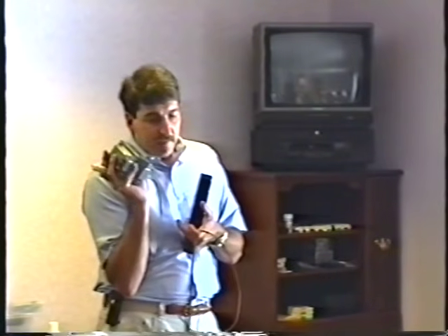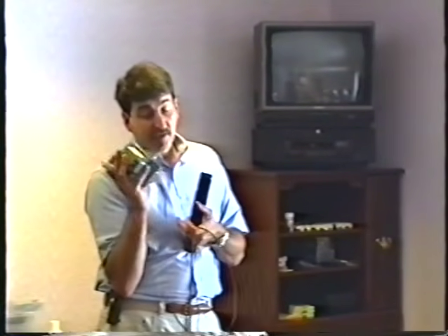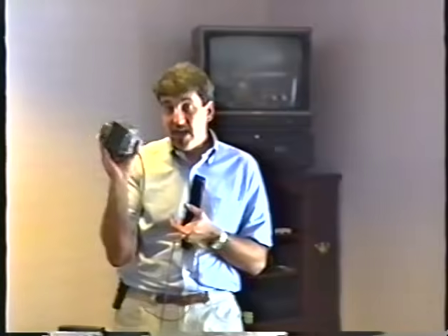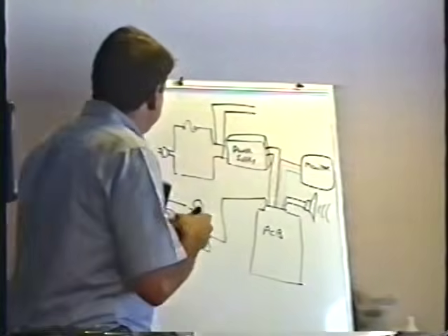Without the isolation transformer in it, the monitor will have 120 volts on the metal chassis of the monitor. Meaning that if you are grounded somehow and you touch the metal chassis, you shock the living daylights out of yourself, number one. Number two, if you actually ground the metal chassis of the monitor without the isolation transformer powering it, you just blow the snot out of it. You'll blow up the monitor, you run the risk of damaging the logic board, all kinds of stuff. So in every video game, there is an isolation transformer that's used strictly to power the monitor.